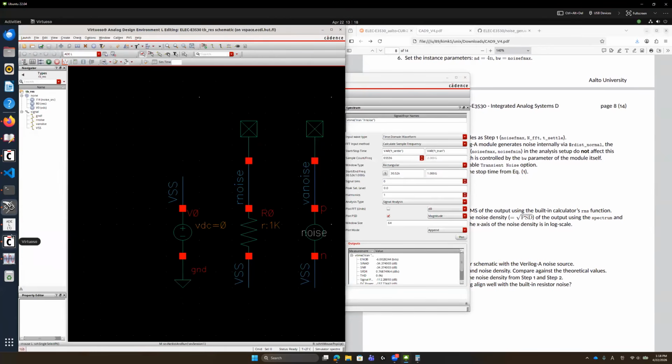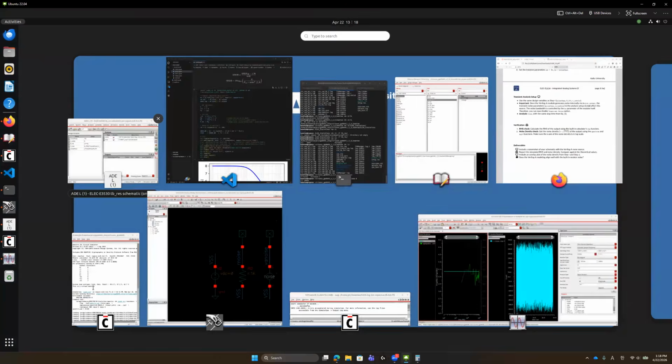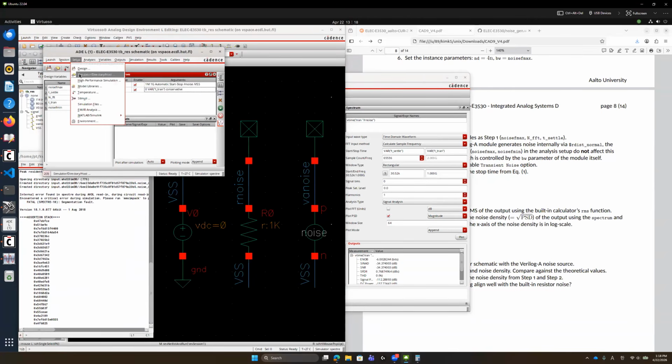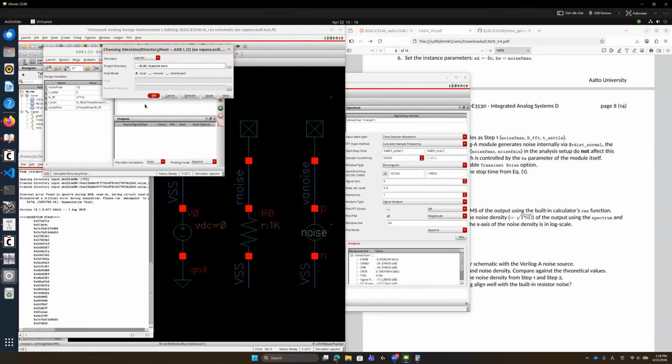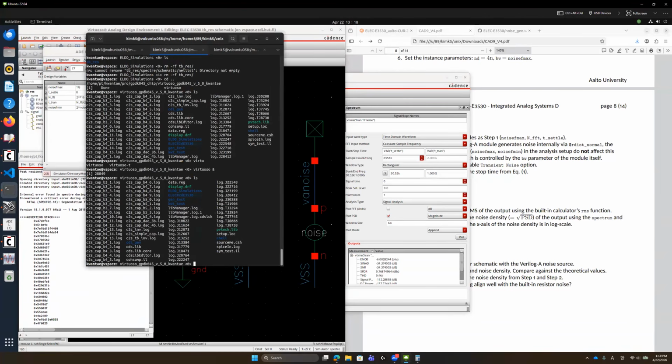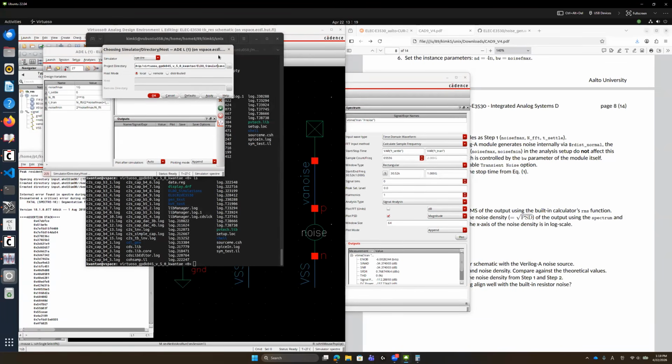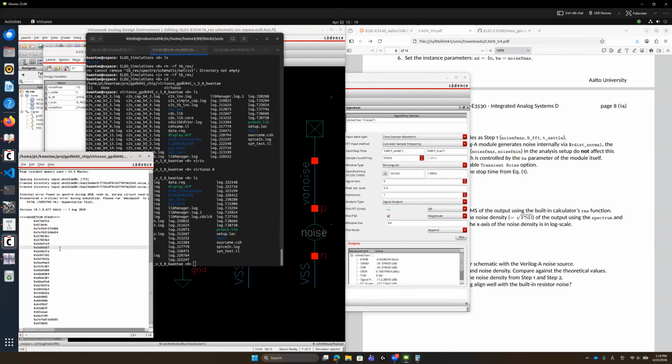Okay, looks like it is completed, but let me double check if there was any error. Okay, there's some error. So in this case, it is better to check the project directory here. There is an Aalto simulations folder, though we don't use the Aalto setup. At Aalto University, we use this folder for noise simulation files, not this simulator one. Yeah, here, project Aalto simulations. It will be different when you design in different environments. For example, in other universities, the simulation files will be stored in different paths. So you can find where it is stored if you happen to see this kind of error.